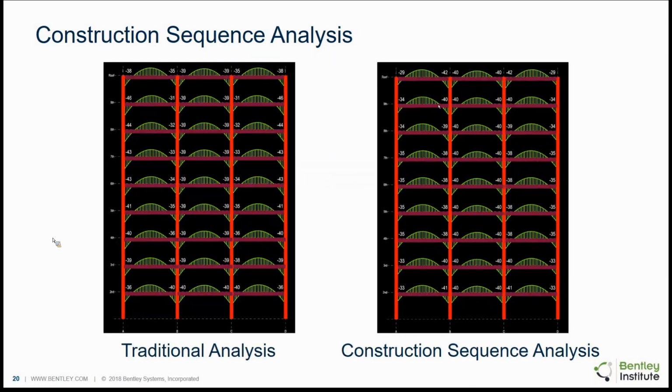So let me go back to the presentation. I have a few questions that came in here on the construction stage analysis here in RamFrame. Okay. First question, is RamFrame adjusting the length of the column braces wall heights between each stage to put the top of the steel and concrete at the ideal elevation? And Blunt can correct me, but I believe that yes, it is, that when it creates that next stage, it's putting it back at the elevation that the floor is supposed to be at, and so it's correcting for the shortening that has occurred in the previous analysis.